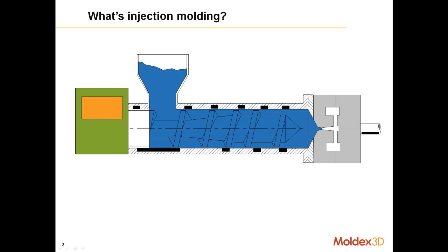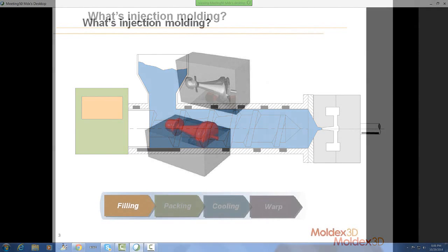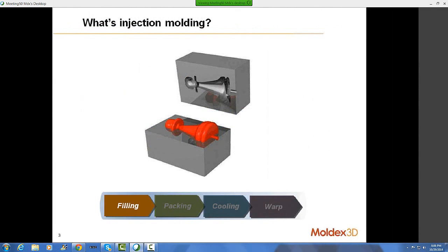Okay, and we all know that cavity filling is a key step, because cavity filling is a process of moving melt front in 3 dimensions and a transition phenomenon. Non-Newtonian flow and coupled heat transfer are usually issues in the filling process. So in general, during the filling stage, product defects will occur if there are design flaws, improper process, or improper material. Then packing is to analyze the packing or holding process in injection molding.